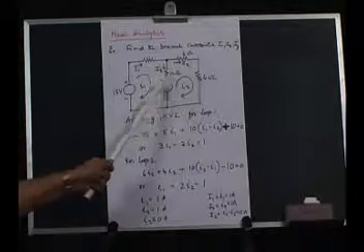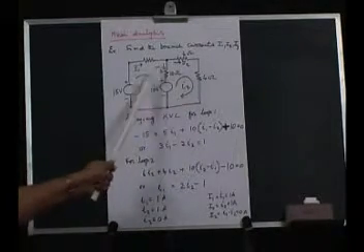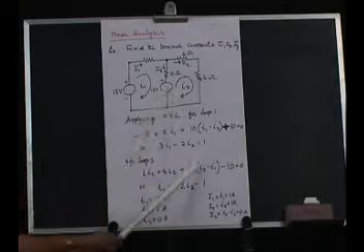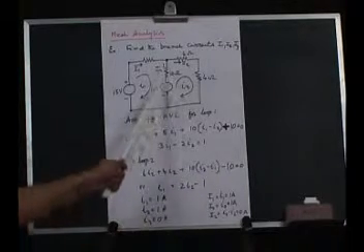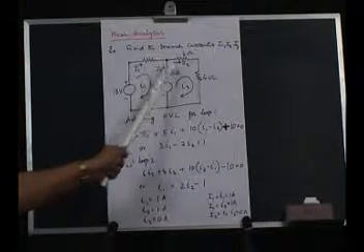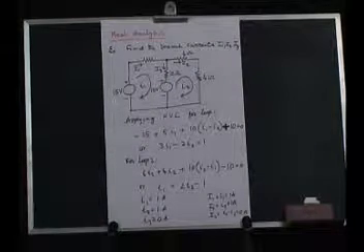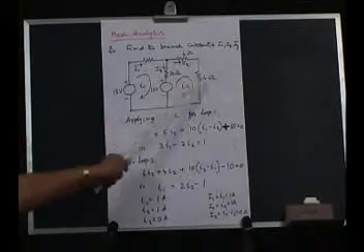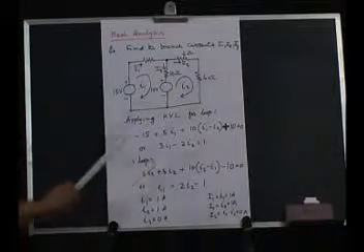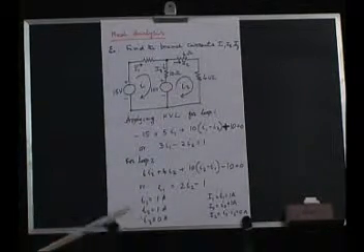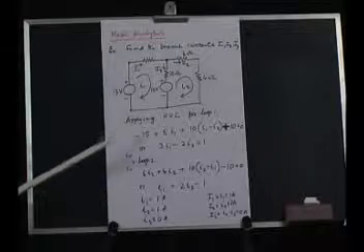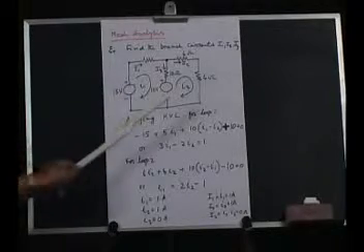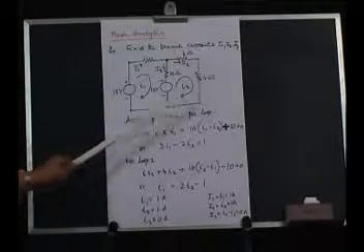And then here there is an interaction of the first current and the second current: 10 into (I2 minus I1) is the drop here. I2 into 6 ohms is the drop across the 6 ohm resistance. Same, I2 into 4 ohms is the drop across the 4 ohm resistance. So, we have written Kirchhoff's voltage law for the first loop and for the second loop.